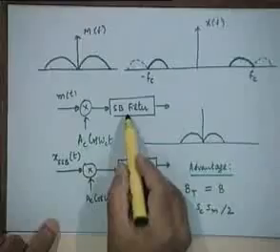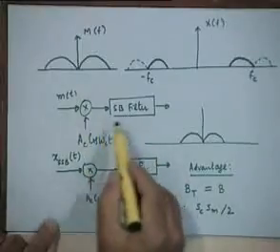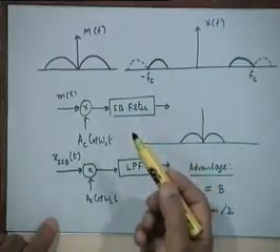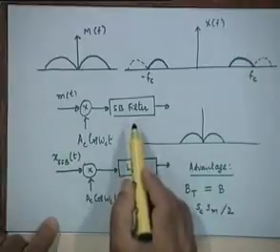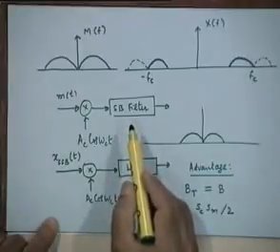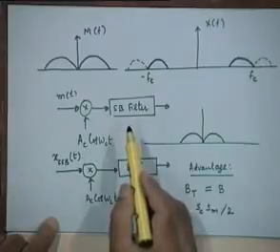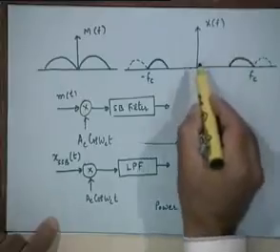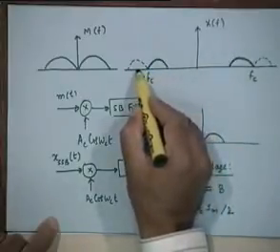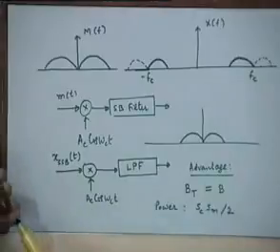Let's discuss briefly the issue of practical realization of the SSB waveform. The additional thing that you require on top of what you do in DSB-SC is this sideband filter, right? Now, this is a non-trivial operation that you want to do. This is what you need to understand. You require a sideband filter with almost ideal characteristics. Suppose you decide to retain the lower sideband, right? So what kind of transfer function should the filter have?